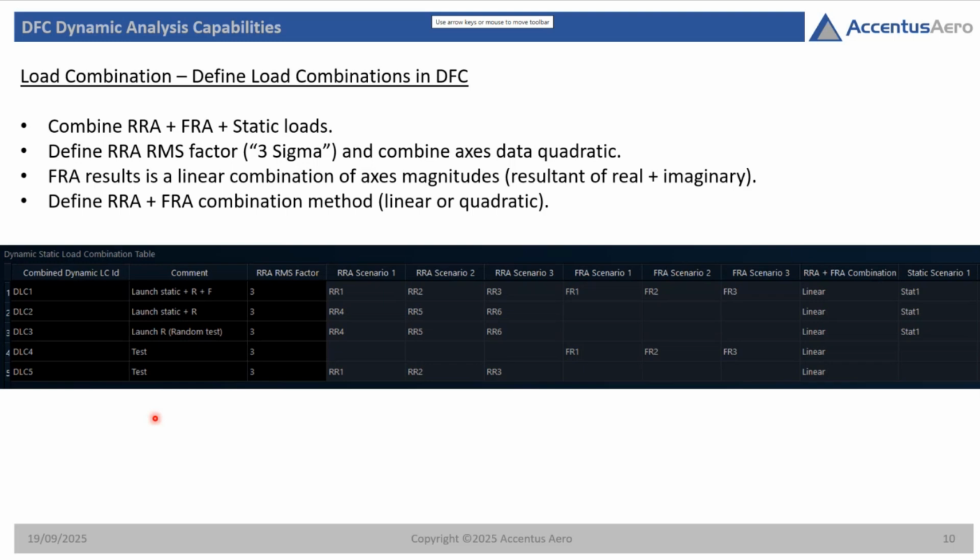The middle option is you use a linear combination of magnitudes by frequency, ignoring phase. The most time-consuming process is you do not ignore phase and frequency, so you do some fancy calculation to get your magnitudes from them. So those are the three options. We take the middle option: we ignore phase and just calculate the magnitude, and we add the data by frequency to get the resultant loading at the three axes.